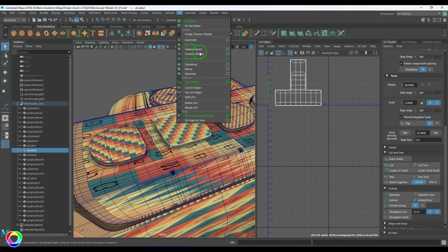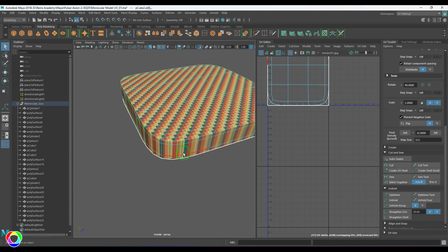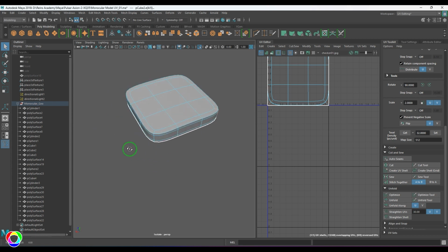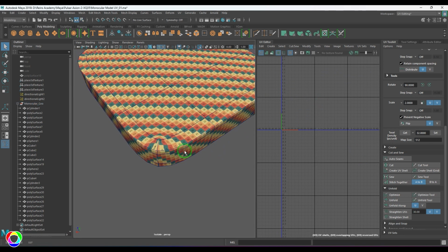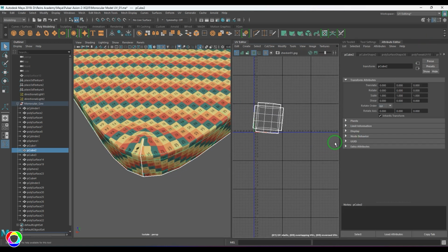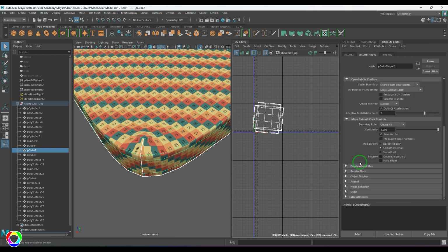So I'm going to apply a planar mapping again. I'm going to select those corner lines. Okay, I'm going to cut UVs and then apply unfold. Press 6 on the keyboard. Now you might be thinking there's some problem here. That's nothing to worry about. You can go to the attribute editor, go to the smooth mesh, and then you have an option for UVs. Then preserve UV adjacent corners will generally fix it.